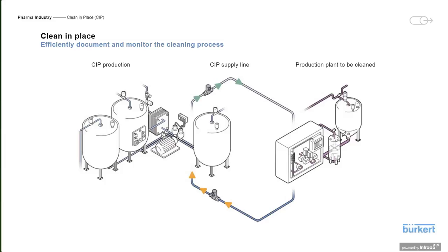Along those same lines, I'd like to point out that FlowWave's built-in temperature measurement may be a good option depending upon your application as an opportunity to reduce an additional temperature sensor or RTD in this case. It's very effective, a multi-parameter function in a single device. Couple that with its hygienic full bore design, and this is why I get very excited when we talk about CIP and the application of FlowWave.